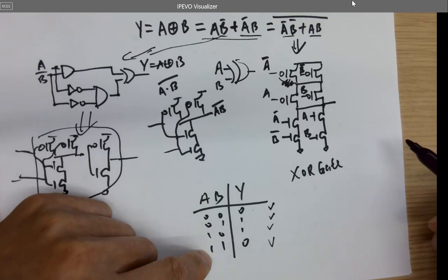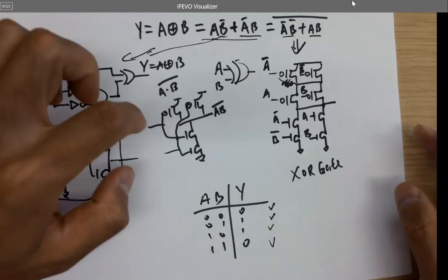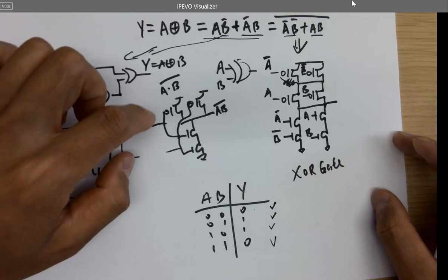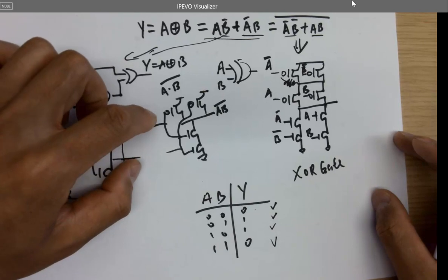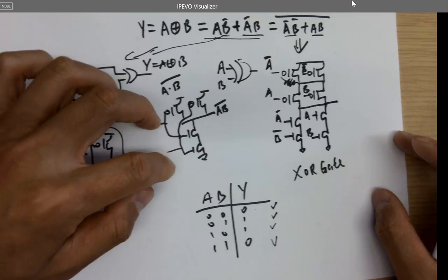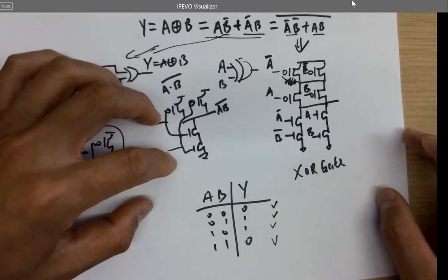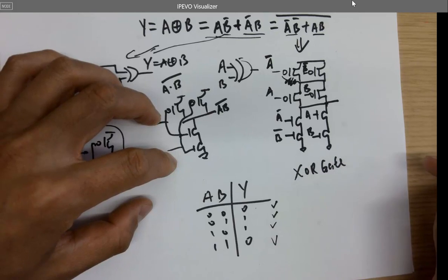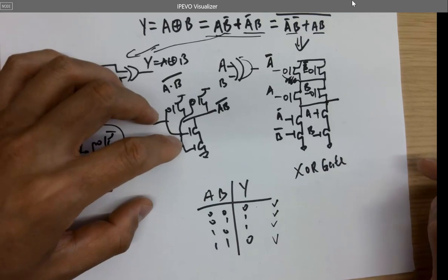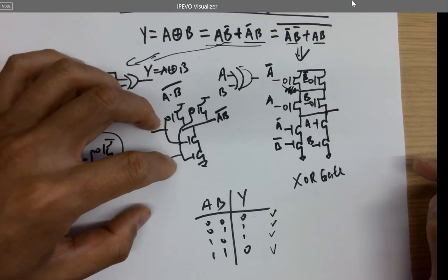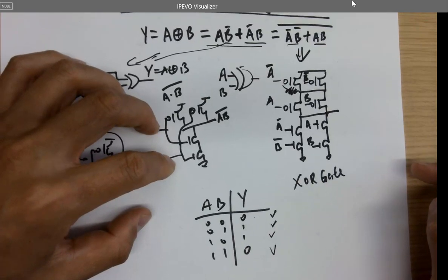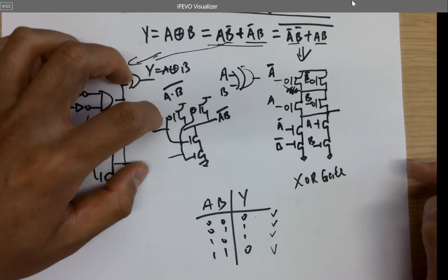So how do you look at that expression and you just know that you need to do it opposite for the PMOS and the NMOS? Yeah, that's the experience that came from this. At the very beginning when we designed the NAND gate and NOR gate, we found out that's the way we have to do it. It's switched like that because the property of PMOS is passing the 1 when 0 is at the gate. So it's sort of automatically incorporating another bar into that expression. Yeah, because PMOS is connected to the VDD and you need a 0 to turn it on.